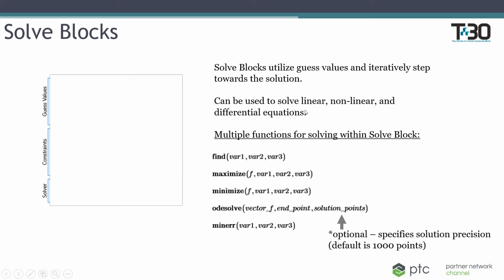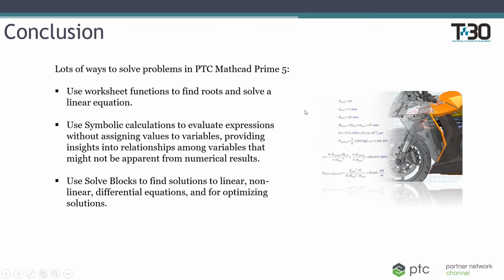Getting back into our presentation here. In conclusion, there's a lot of ways to solve problems in PTC Mathcad Prime 5. You can use the worksheet functions we have to solve roots or solve a system of linear equations. You can use symbolic calculations to evaluate expressions, and you don't have to assign values to those variables. You can get some valuable insight into the relationships between the variables that might not be apparent just from looking at the numerical results. Solve blocks are also really great at finding solutions to systems of linear and nonlinear equations, differential equations, and even optimizing solutions.